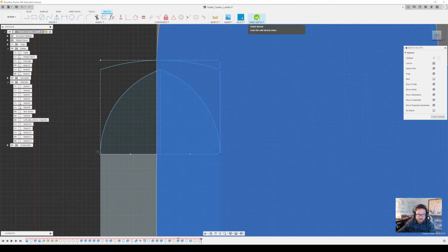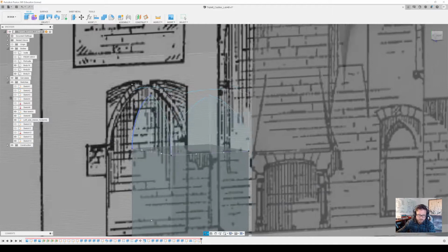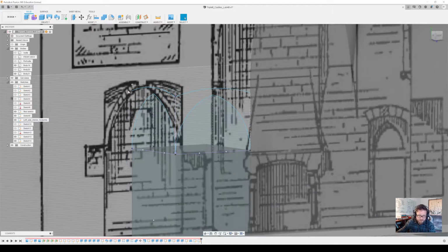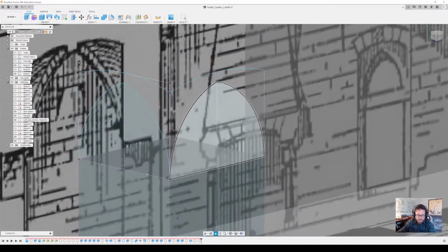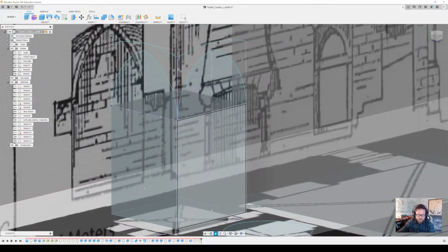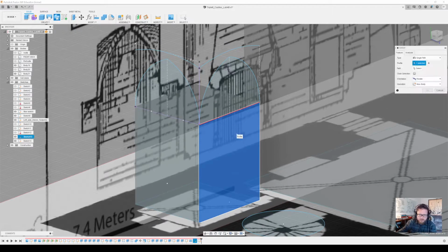So let's hit Finish Sketch. We're ready to go. And if I hold down Shift and show you, this is basically what you're going to draw. Now you can actually leave the cross piece right here if you really needed to. You could have just dotted lines across here, just guides. But for me, this is going to work out just fine. The next step is to do a quick sweep, and we're going to do a different kind of sweep than we've done before. This is going to be a parallel instead of a perpendicular sweep, and I'll show you that really quick here. So I'm going to select these two profiles, and if this is set to perpendicular, which often, and also if chain selection is on, deselect this, but you'll see why.